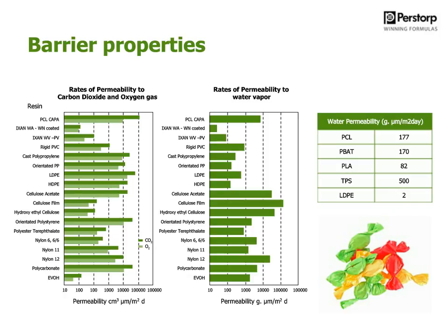And we have also done some comparisons when it comes to water vapor permeability, where we have included some other polymers like PLA and TPS, as well as PBAT on the right-hand side, to get an overview with the most commonly used polymers in this field today. They are not included in the graphs next to it. So you can get an idea or find a comparable material, and also how you can formulate to improve these barriers. But in most cases, you combine multiple layers, so you can still introduce a biodegradable or bio-based component, and in the end, achieve the barrier you're targeting.